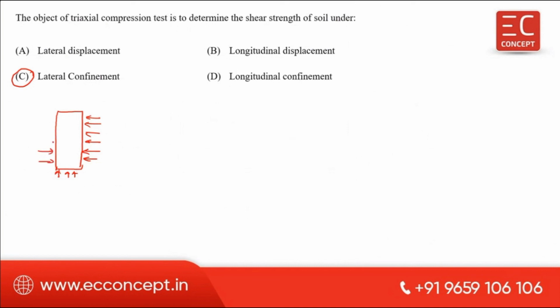Once we finish this, keeping the confining pressure sigma 3 constant, we apply a direct load, that is the deviator stress.